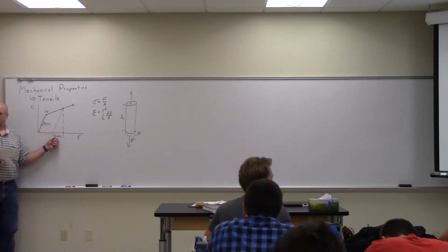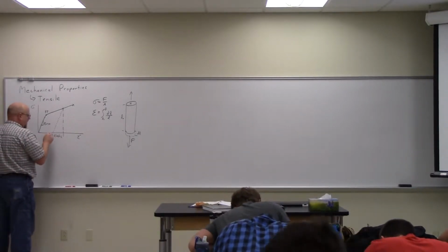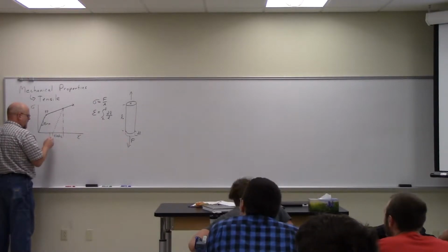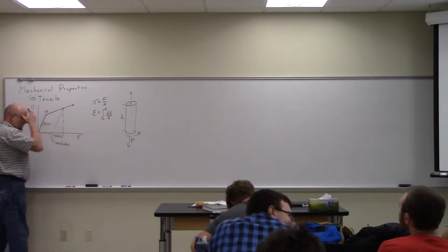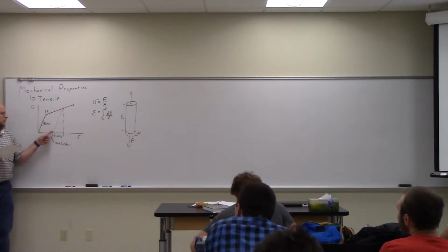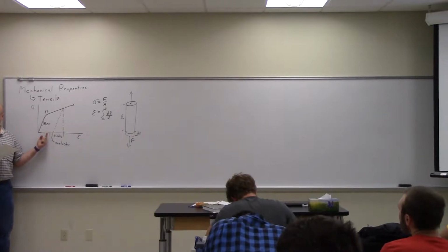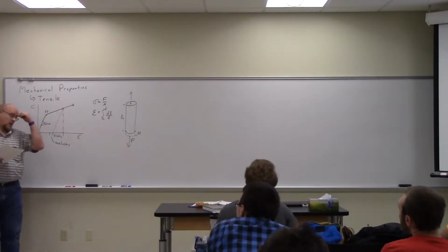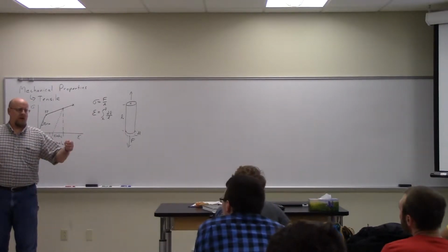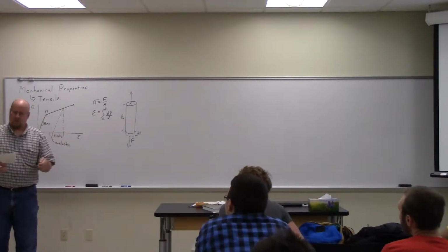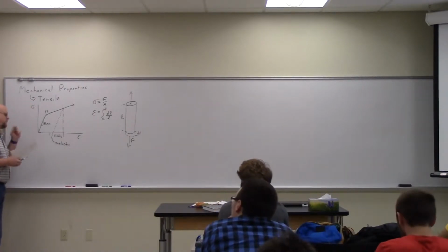Alright? Elastic. Everybody understand elastic, because it comes back. There's actually a little bit in here of what's called anelastic. That is, when it releases, it comes back to here, and then if you let it sit, it'll recover some of that. If anybody's ever stretched a piece of silicone or something, and then let go, and it comes back, and then it kind of shrinks back a little bit more. You know what I'm talking about? Okay, so that's the anelastic piece.